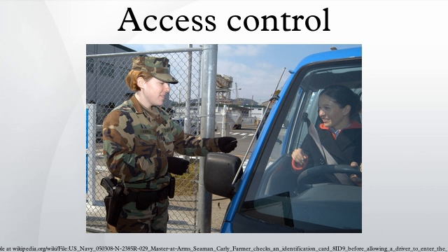The predominant topology circa 2009 is hub and spoke, with a control panel as the hub, and the readers as the spokes. The lookup and control functions are by the control panel. The spokes communicate through a serial connection, usually RS-485. Some manufacturers are pushing the decision-making to the edge by placing a controller at the door. The controllers are IP-enabled, and connect to a host and database using standard networks.